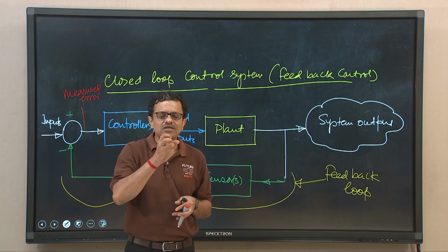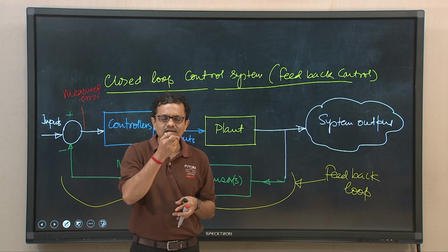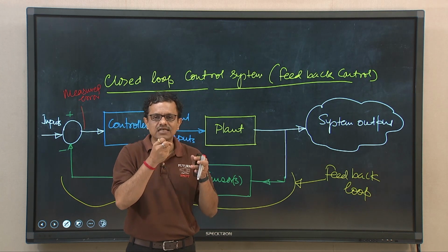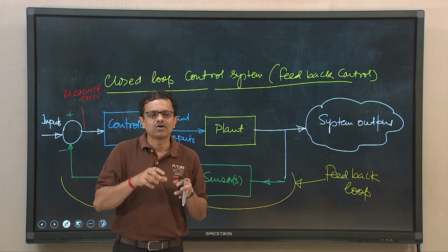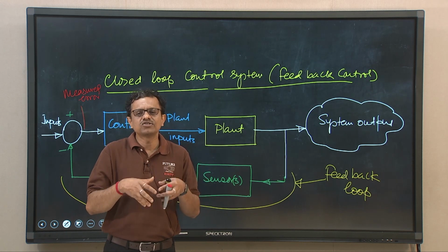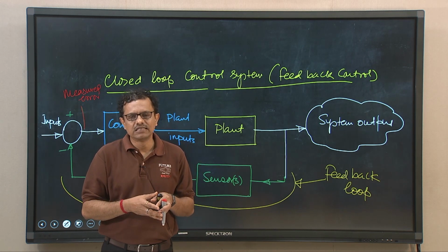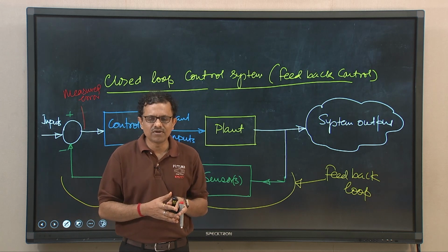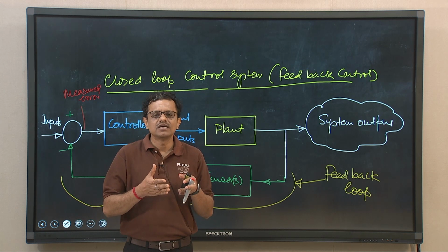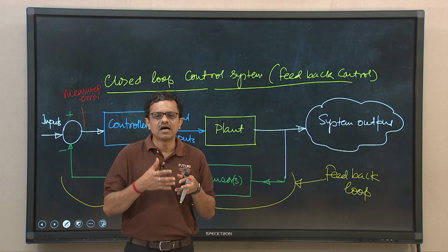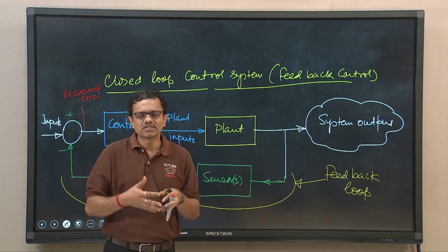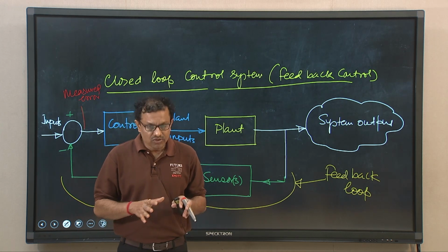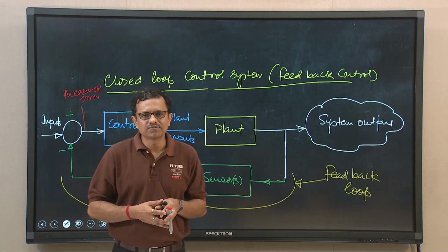That means either increasing the fuel injection period or time, or increasing the throttle valve position or opening area, so that the stoichiometric air fuel ratio is always supplied to the engine, and then efficiency will be maximum. Oxygen content in the combustion gases will not be either high or low, and catalytic conversion efficiency also will be maximum. So, this is all about these two different types of systems.